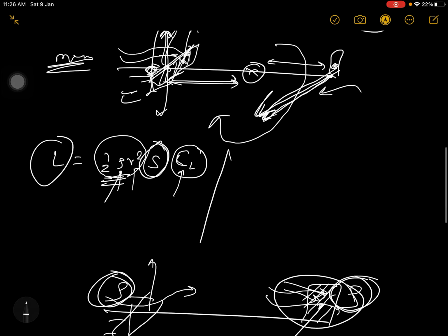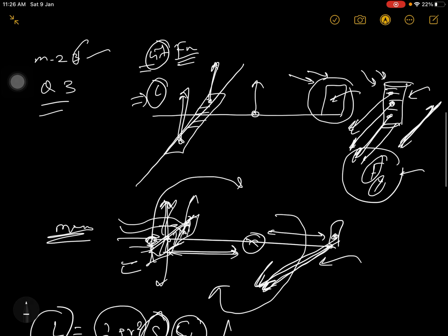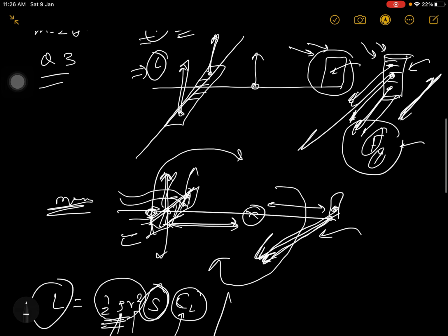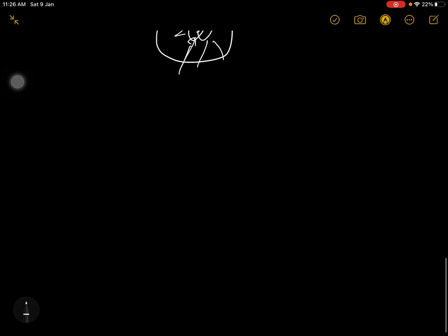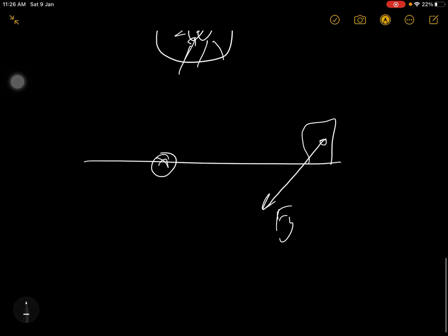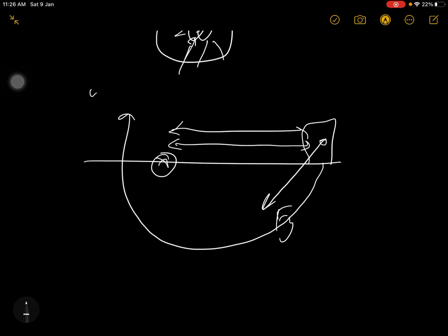After that, once your Fy is done, as I explained, when the force is acting you multiply with the distance from the CG. I mean to say, here is the fuselage reference line, suppose you have the CG here and here you have your tail, and the tail is producing some force Fy here, and this is the distance. Because of this distance, your Fy will produce a moment here, and that will be yaw in nature, correct?